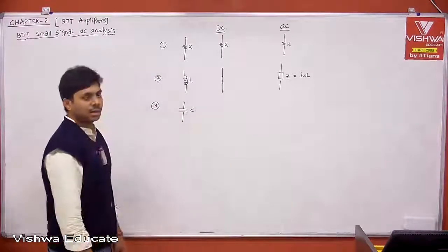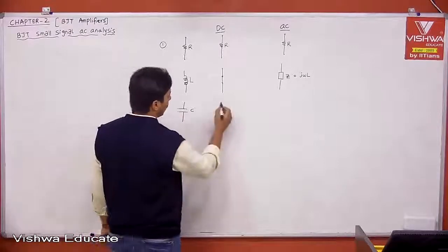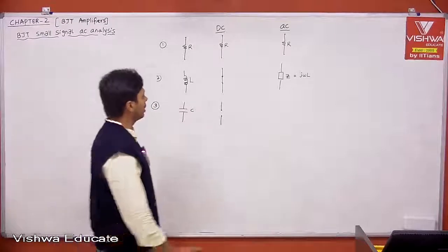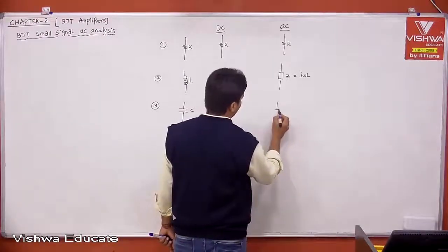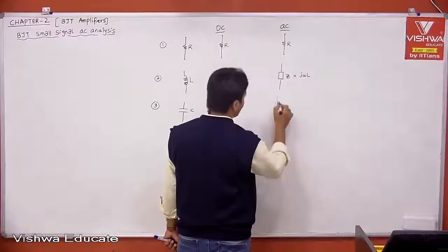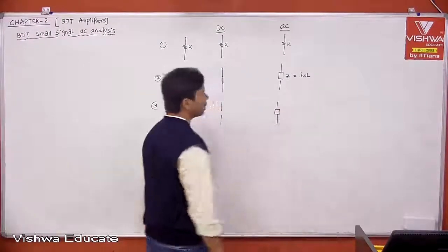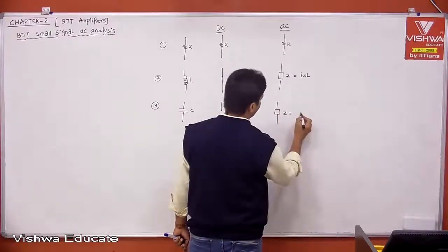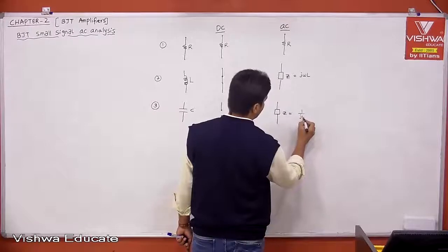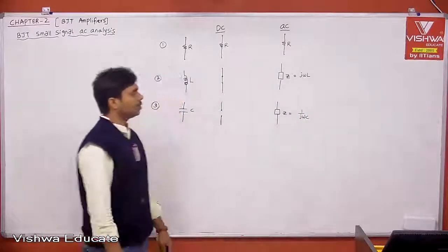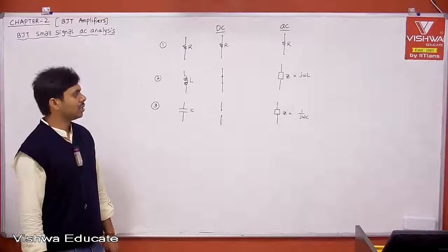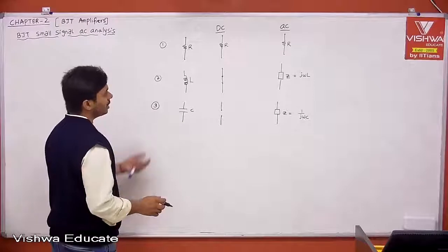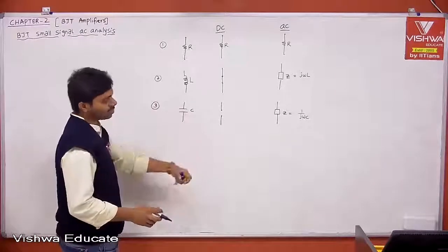Now if you take capacitors, for a DC, the capacitor acts as an open circuit, and for AC, the capacitor acts as, it is not a short circuit, but it will have connectivity between two terminals. Okay, then if you take the Z value, that Z is equal to 1 by J omega C. You can take the manual and all later, but that is the Z, which is offered with respect to the frequency. Now actually using these things I am going to exploit it next.